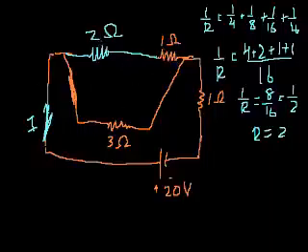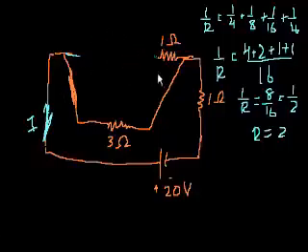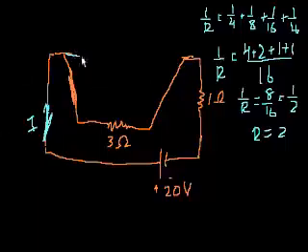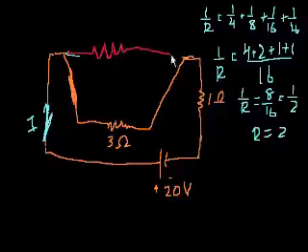So let's erase and simplify. So then we get that combined resistor, right? We had the 2 ohm that we had simplified, and then we had a 1 ohm, and whoops, I'm using the wrong color. So we had a 2 ohm and a 1 ohm in series, so those simplified to 3 ohms. Well, now this is getting really simple.